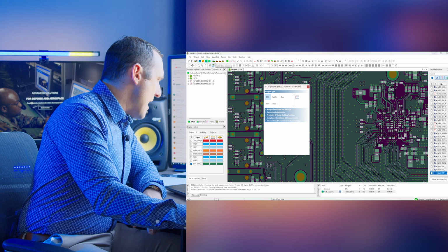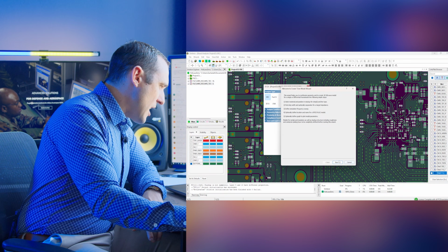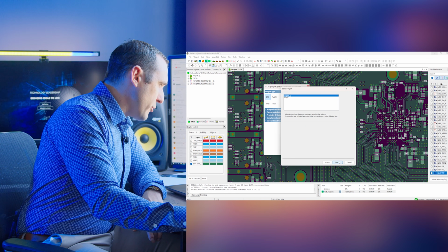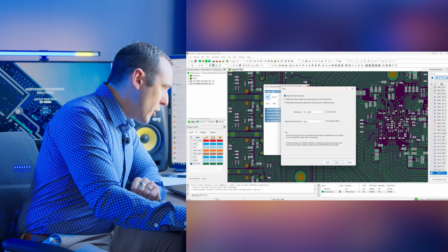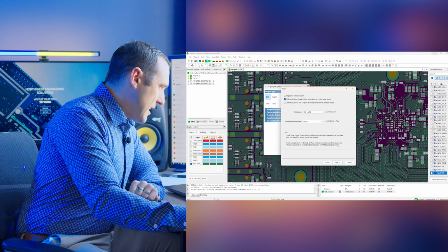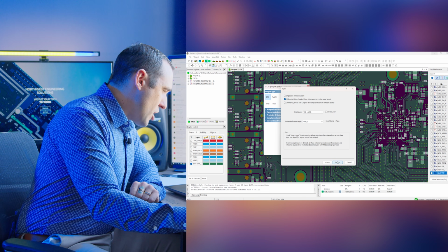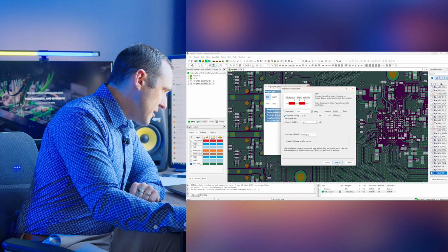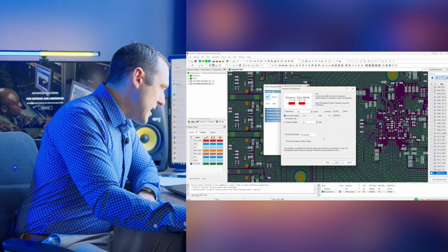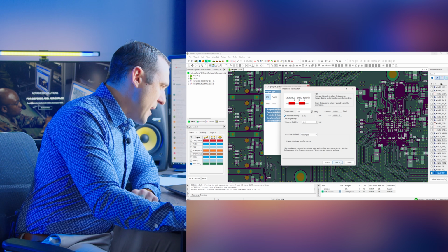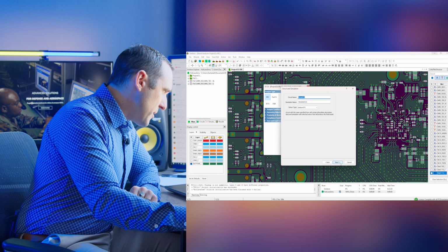So you can see here I have an option to create a T-line model. I can then go through and create a model on my existing stackup. I can just kind of follow this wizard. If I want, I could, for example, create edge-coupled strip lines on one of my layers. I can just kind of click through here. You can see here it automatically calculates what is the trace width and spacing for a 100 ohm impedance.